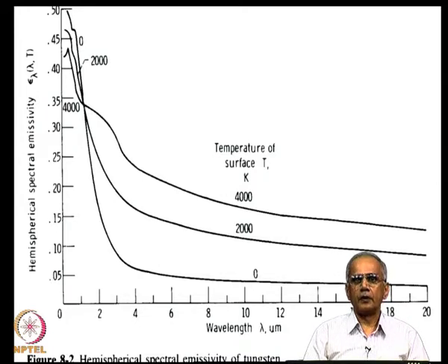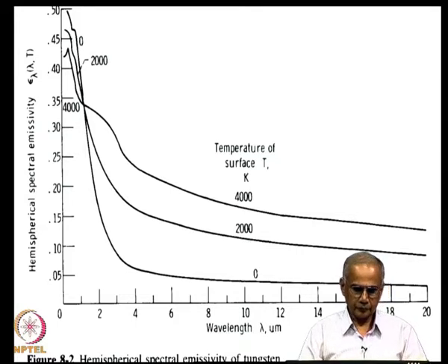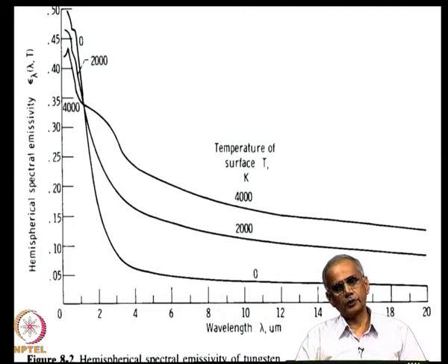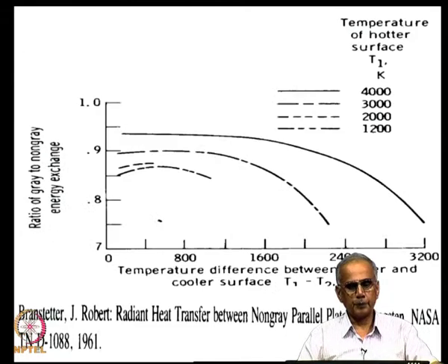So, that completes our discussion on enclosures with diffuse isotropic reflectors and emitters and gray and non-gray surfaces. Now, there are some situations that we encounter, especially in application to solar energy use, wherein the surface you have is not a diffuse isotropic emitter or reflector. Very often there are surfaces which are reflecting like a mirror. Okay. Such surfaces are called specular.